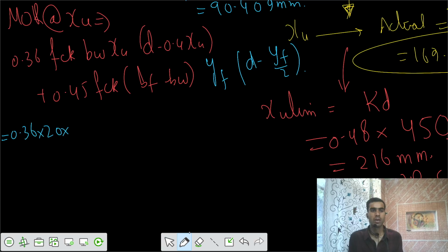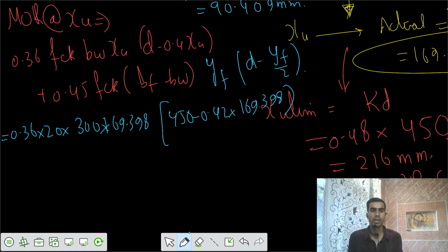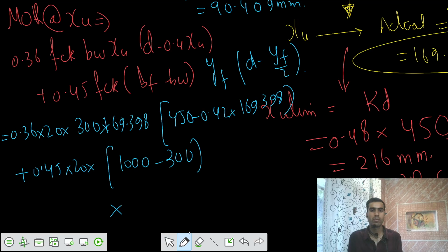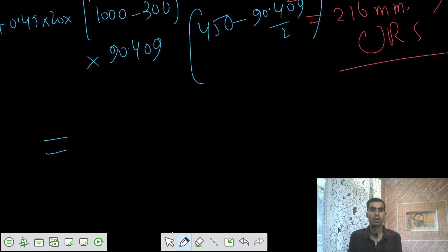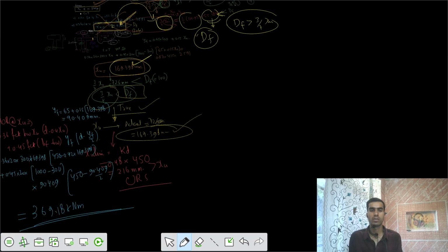0.36 FCK, BW, XU, and D minus 0.42 XU, actual, and we have this 0.45 FCK, and we have this BF minus BW, and we have this YF also, 90.409, into D minus 90.409 divided by 2. So that's your calculation for moment of resistance. So the final value would be equal to 369.18 kilonewton meters. This is your moment of resistance.